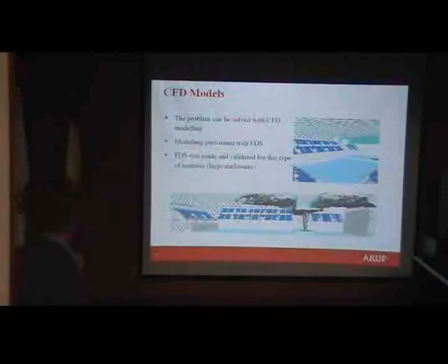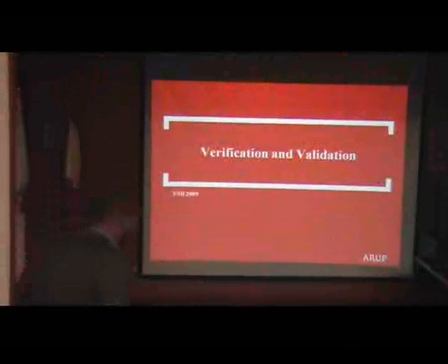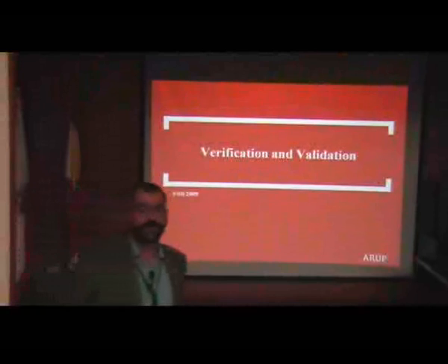In this case, this is a project that we have done and it was solved with FDS. FDS was actually created and validated for this kind of scenario. So I'm quite sure that, with the normal uncertainty that the model has, I can rely on this model. And then another important thing is the verification and validation.